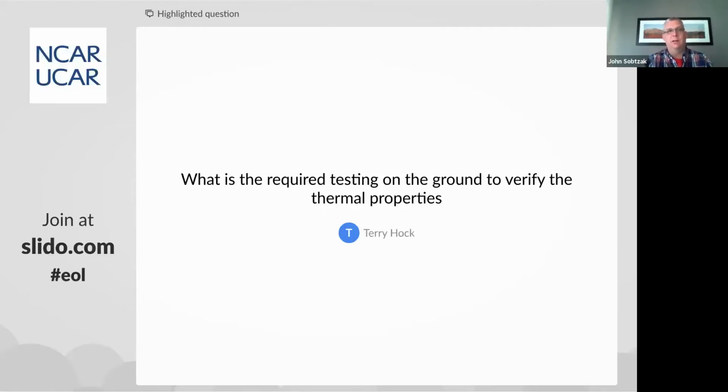The hard part with testing anything in a chamber is testing the radio, because you don't want to transmit inside of a chamber. They often put things over the antennas, we were just talking about this yesterday, hoods of some kind. But yes, there are testing requirements. Our test plans usually say, put it in a thermal chamber, heat it up to 60 degrees Celsius, turn it on, check out the systems, hold it there for an hour, cool it to minus 50 degrees Celsius, turn it on, make sure it works, and things like that. If that's what you're getting at.